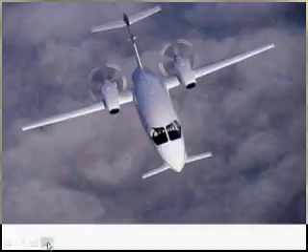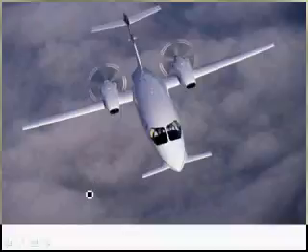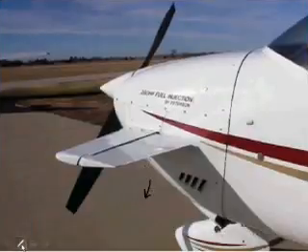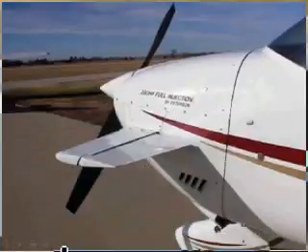And of course, oh wait, here's the canard. It's putting a wing out in front. Typically on aircraft with canards, the canard is at a slightly lower angle of attack, so it's going to stall first, and that makes the nose go down, and you recover from the stall automatically. I won't go so far as to say canard aircraft cannot stall, but it makes it much, much, much harder. And of course, if you're flying short takeoffs and landings, you don't want to stall.